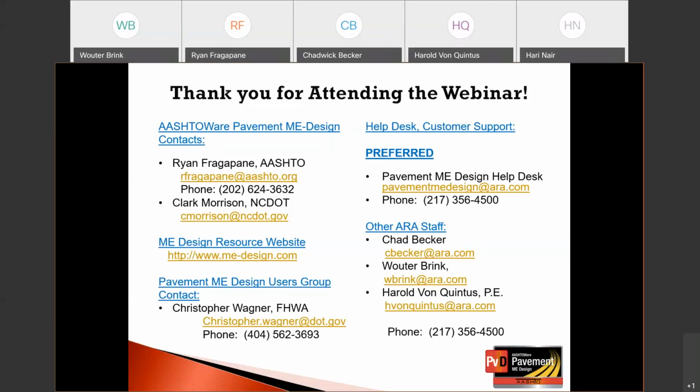Both bottom-up and top-down are treated separately as part of Pavement ME, and then both get combined when looking at IRI. There is a procedure that we use to determine if it's bottom-up or top-down, as an estimate based on the damage value and the measured data. That was implemented when we looked at the top-down cracking model.